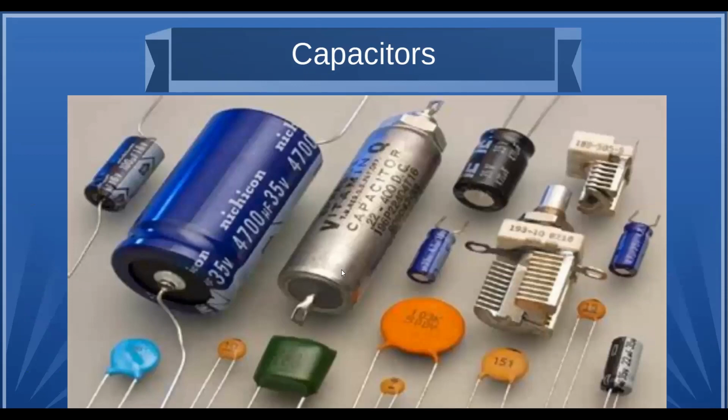This is a picture of an assortment of more modern capacitors. These are electrolytics, which process is slightly different because they use an electrolyte to help migrate the charge. So they can actually hold more per volume than the basic electric field type. These are ceramic capacitors, which are 2 metal plates separated by a piece of ceramic.